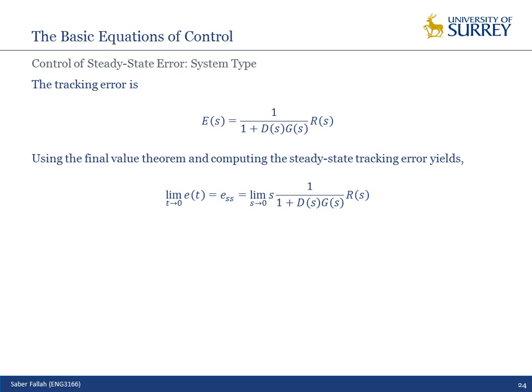When you have a block diagram of a system and you see the input, you can judge what your steady state error will be without calculating the transfer function of the system and without using the final value theorem. So I'm going to give you some tools to check the steady state error of the system based on the given input.